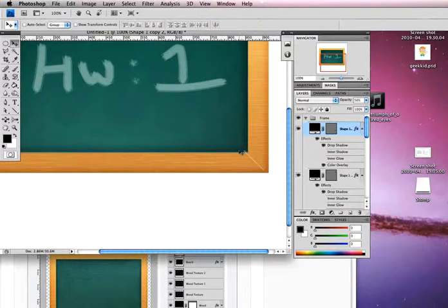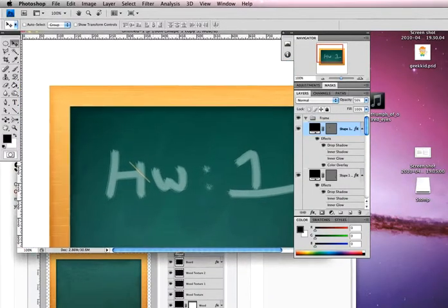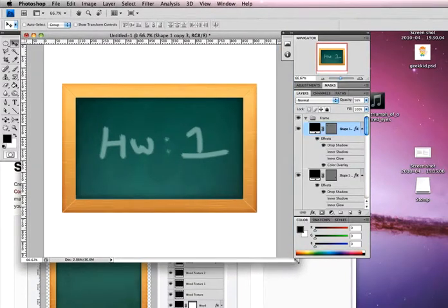And then just nudge that down. V again, hold down Alt, drag that over, and position that. It doesn't need to be perfect as long as it's not going over the edge, which it isn't. Let's take us out. Then you can start to see the edges taking shape, which is really good.